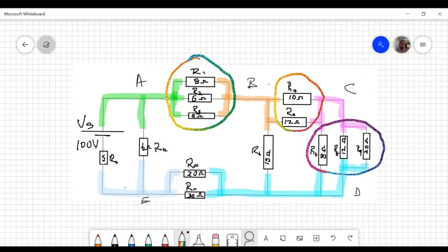But here we can see this 20 and this 30, they're connected together on the input side and on the output side. So that's another parallel group. Again, you may ask, what about the 6? Well, we'll discuss that again. And what about this 5? Let's simplify the circuit one stage and see what we get next.